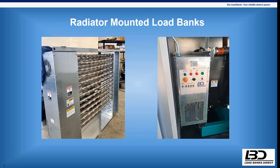And then touching back on these each being custom window sizes to pair with the face of your radiator, that's super important because we need to capture all that airflow. We don't want hot spots on our resistors where they're not catching airflow, or potentially maybe ours was too small for a radiator.